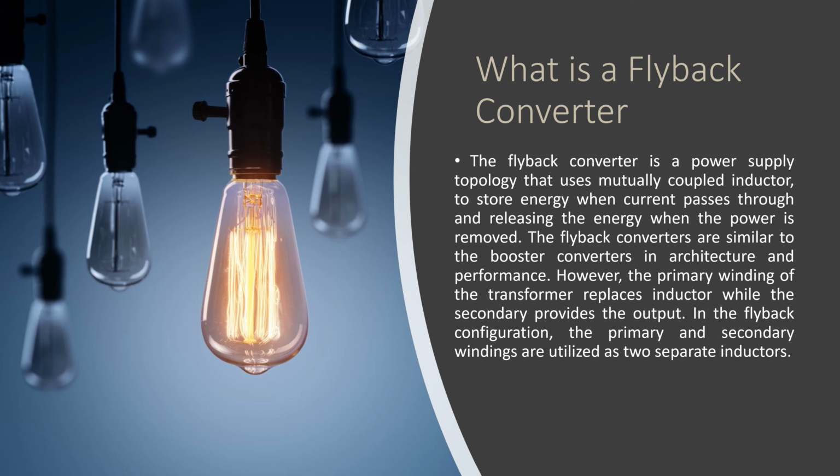Now, what is a flyback converter? The flyback converter is a power supply topology that uses a mutually coupled inductor to store energy when current passes through and releases the energy when the power is removed. The flyback converters are similar to the boost converters in architecture and performance. However, the primary winding of the transformer replaces the inductor while the secondary provides the output. In the flyback configuration, the primary and secondary windings are utilized as two separate inductors.